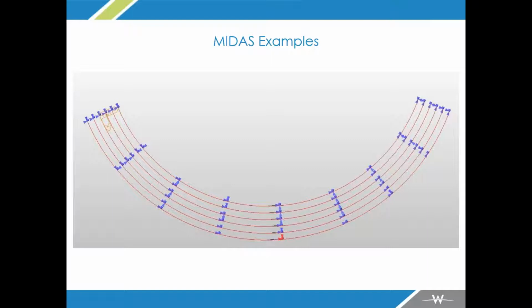I did do this, and I didn't pull this one up, but I did a failure analysis on the Jennings-Randolph Bridge, which is, there's approach structures, multiple curved structures coming into one, and then they go across one of the largest Pratt trusses in North America over the Ohio River. But they had failures, bearing failures occurring and starting to propagate into the beams.